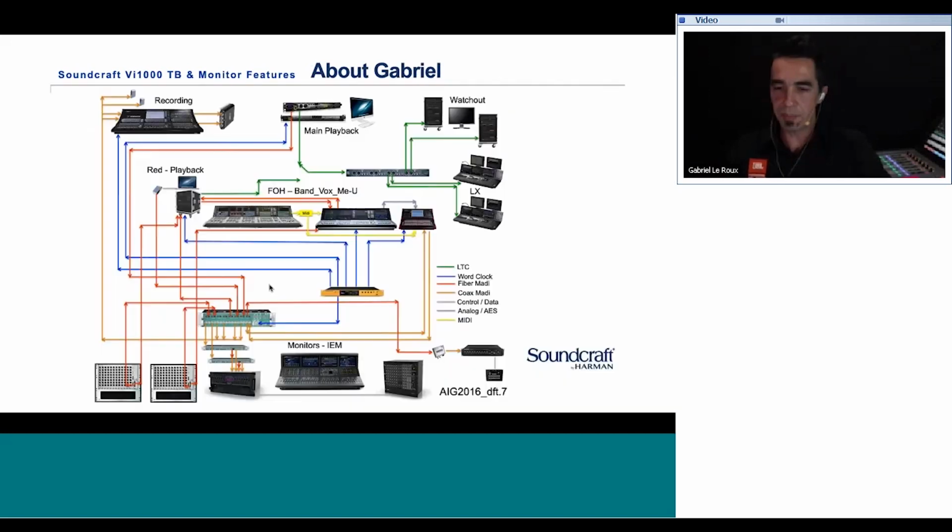One of my other passions is signal integration. How do we make different pieces of hardware work together and talk to each other, when it comes to triggering them via MIDI or timecode, or distributing signal at different sample rates? This is something I can talk about for a long time. Here's a design that I did for a show called Afrikaans Groot, where one half of the setup was running at 48K and the other half at 96K, with all kinds of interesting stuff happening there.